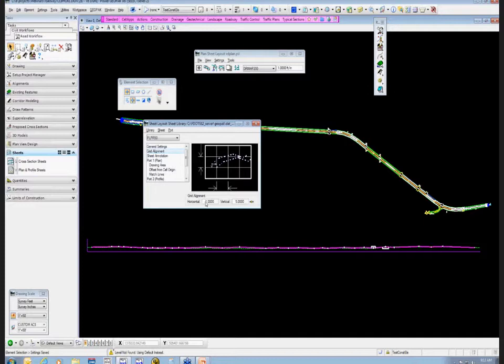Basically what this does is this sets it up so when you start placing clip borders, this tells it the accuracy that you want it to use so that it lines up on our grids. For the horizontal, what you're going to find is that they're set to 1. That way it puts it at an even station.